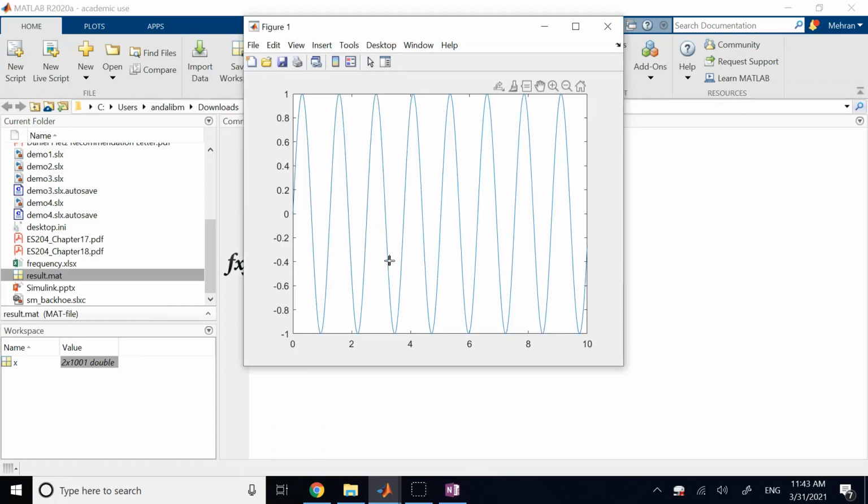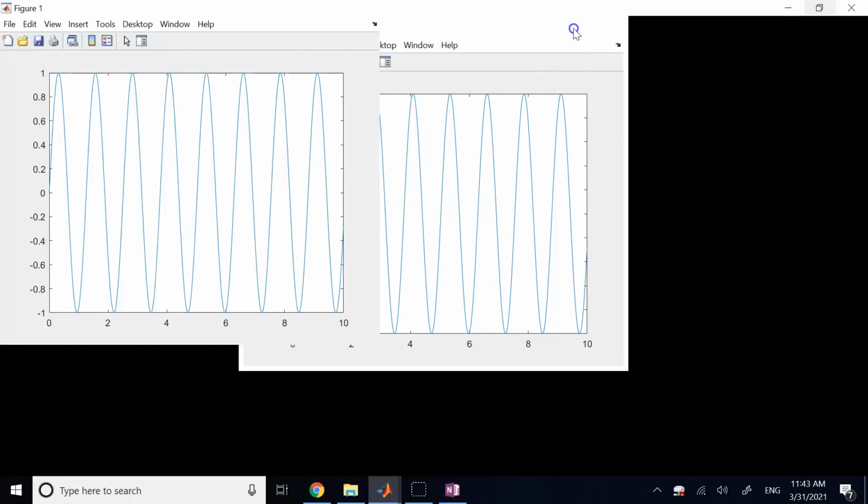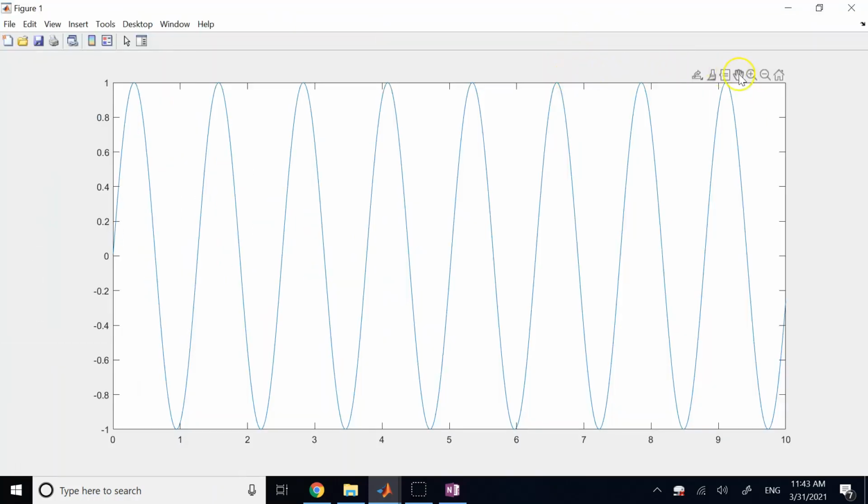Okay, and you clearly see this is a sine function, and if you measure the frequency using this cursor, right? So if you can find 2 points that are corresponding to each other, if you click here, for example, you see that the X, which is the time here, is 0.63. And then I'll try to click on the next corresponding point. So I need another data cursor. So I hold down Alt and click to get one more of that. Because if you don't, it is going to clean this up and put that data cursor here.